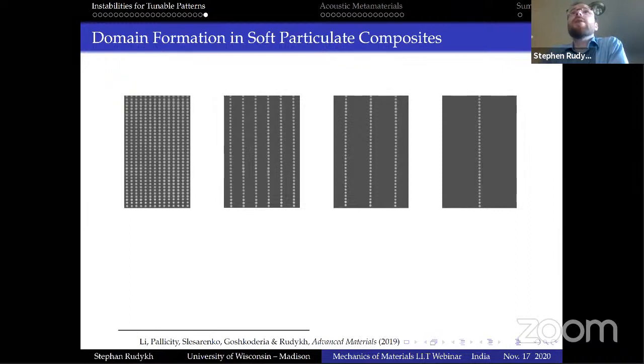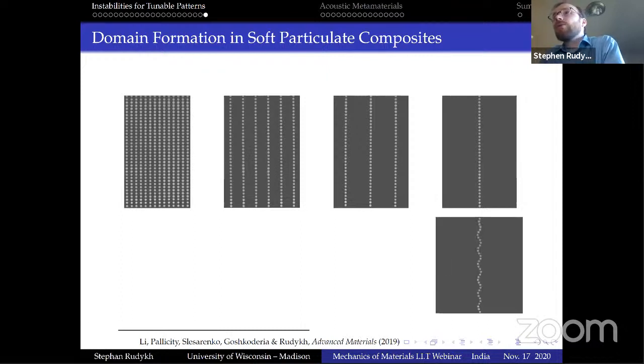And so finally, just to illustrate, or at least initiate some thoughts about the understanding of the formation of these patterns, here is a simple example of the transition from this microscopic to this domain formation pattern. Let's say we have an isolated column of these inclusions, and as I already mentioned, in that case you can consider this column as effectively a reinforced region of the material. So it will behave stiffer, in a way like a laminate.